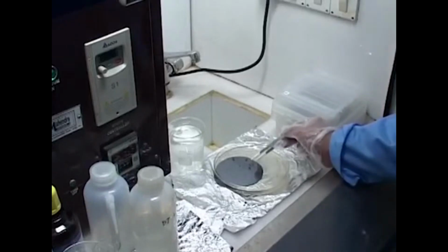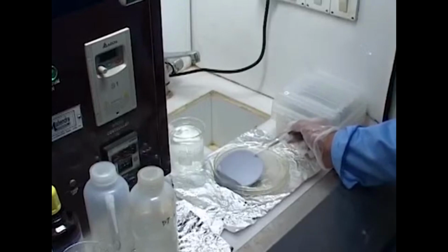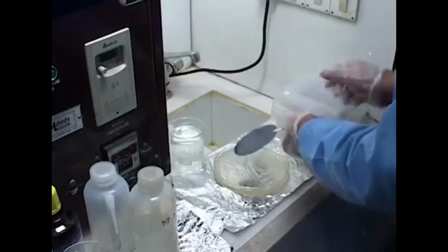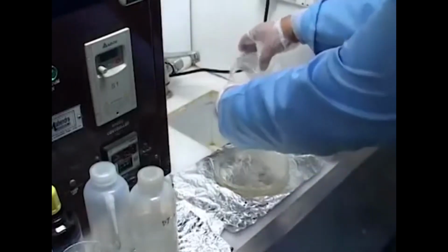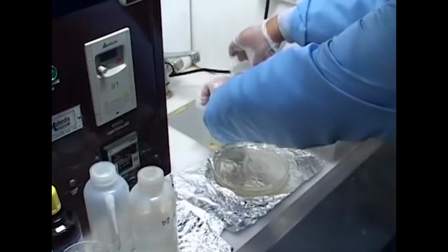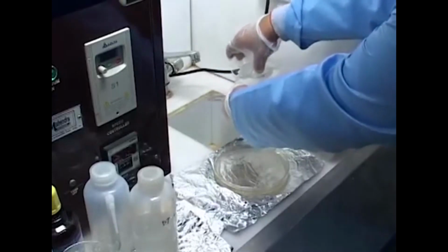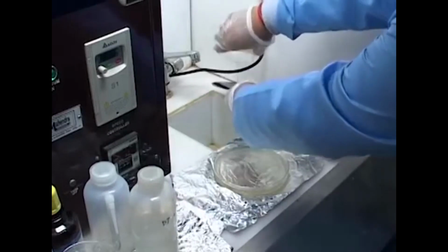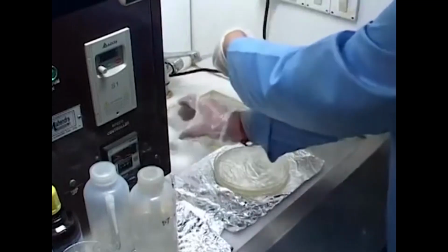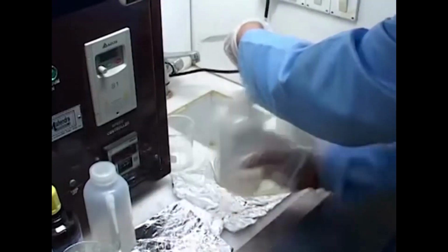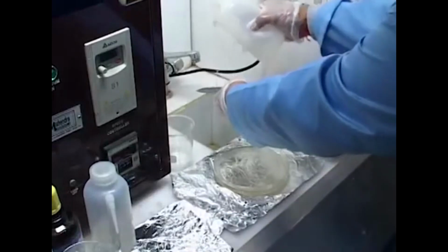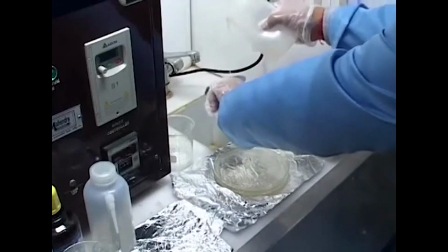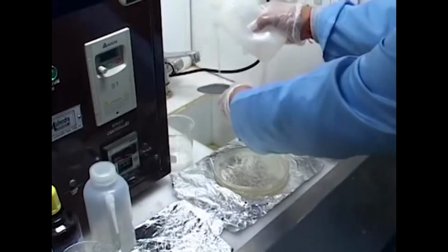So what we do is we basically pull it out very carefully, because essentially this is all acid coated now, and one has to be very careful, and then hold this over this edge and rinse it inside this with water, and rinse it on both sides. As you can see, all the water should typically go and rinse all the acid off the surface of the silicon wafer, and essentially once this is clean, in the next stage what we do is we take this DI water and slowly rinse it on the surface of this particular wafer. As you can see here, this is actually a squirt bottle which is squirting away the DI water on the top of the silicon wafer.